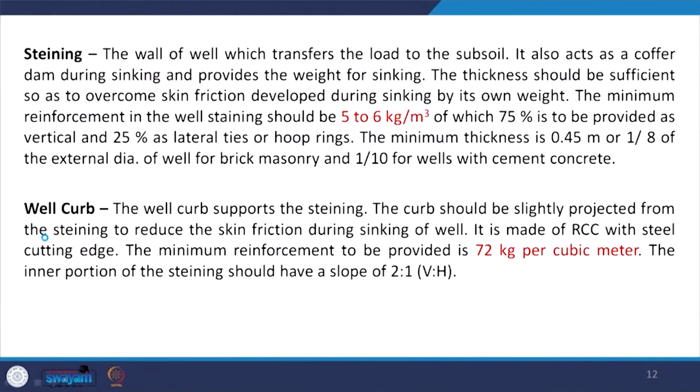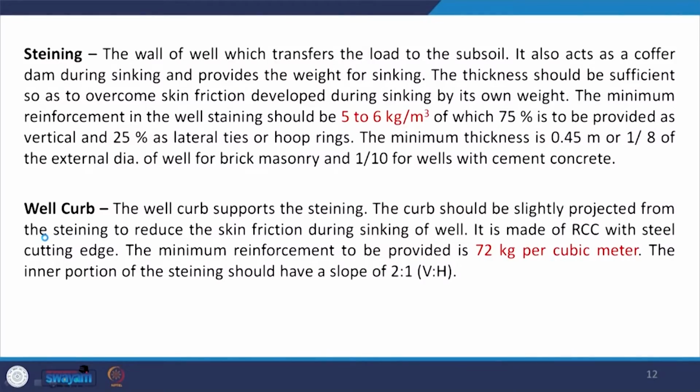So, well steining is shown here, and this also acts as a cofferdam during sinking and provides the weight for sinking. The thickness should be sufficient to overcome skin friction developed during sinking by its own weight. So, what will happen when you sink the well inside the soil, due to the heavy well itself, it should not happen that the side wall or the well steining collapses.